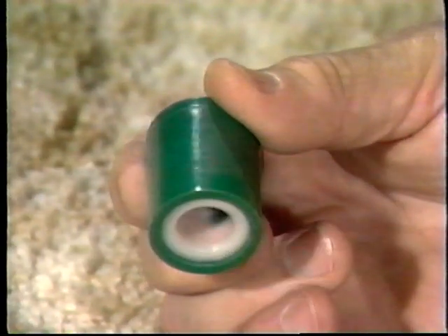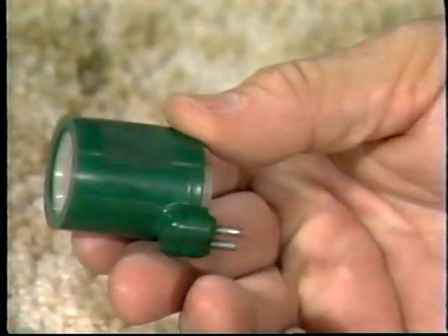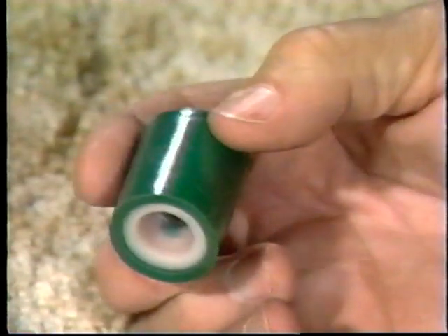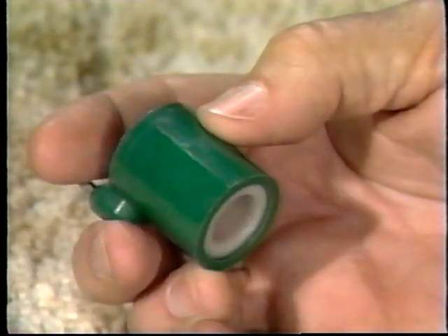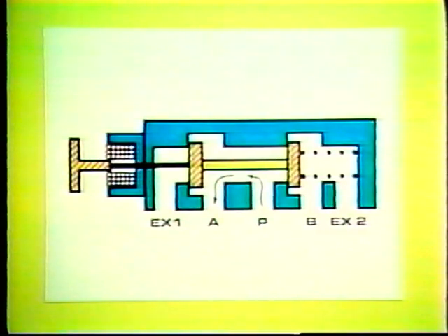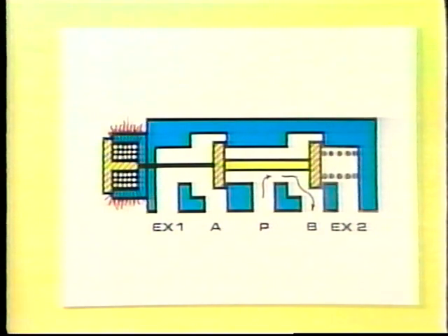When we pass a current through the coil, a force is exerted on the plunger like this. Quite often, the coil for a directional valve actuator is covered with insulation or encapsulated. When a solenoid is used to operate a valve, the electrical current flowing through the coil causes the plunger here to move this push pin. This force shoves the spool over, as you see here.